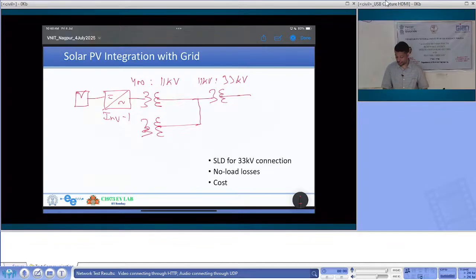Theoretically, there is a circuit breaker here. There are a lot of circuit breakers in this scheme which I have not drawn. Theoretically, you can open those circuit breakers, right? And then you can de-energize those transformers at least for the night if you don't want to use them. But you don't do it because circuit breakers also have a very limited lifespan. People don't want to switch them every night, right?